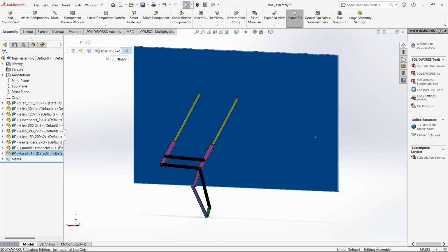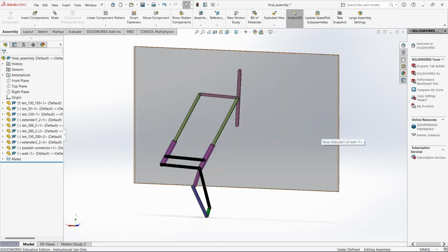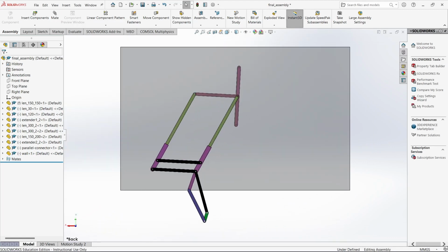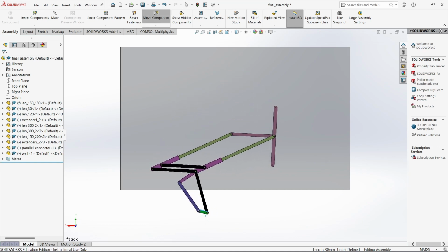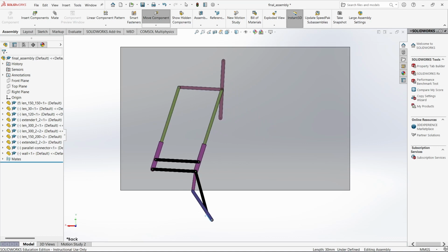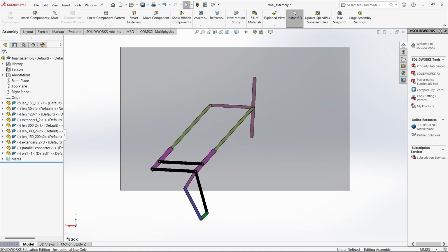And this part is just to mimic a glass wall. If I move this link, it can be seen that this works the way we want without any quick return. I can move it at a constant speed, since I have done that with a motor of constant speed, so we will see that. I have also done a study by varying this length, so that we can see how the area of wiping changes as we change this length.